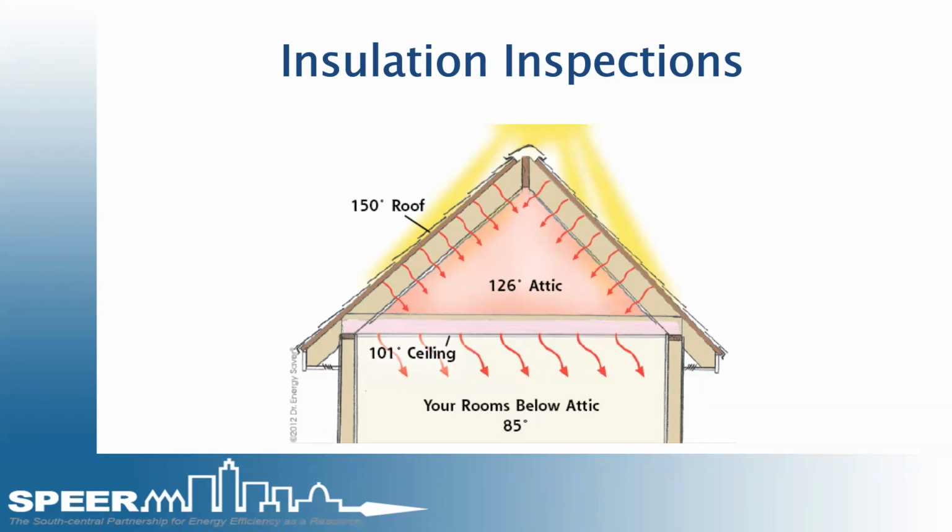That's not just for insulation in the attic, that's for all components of the building. So as long as the insulation is installed properly, and it's also within a 6-sided encapsulation, and you've stopped air moving, because once air is introduced into the insulation, the R value greatly diminishes. So the reason you don't cap, and I had this question asked last week, the reason you don't cap insulation